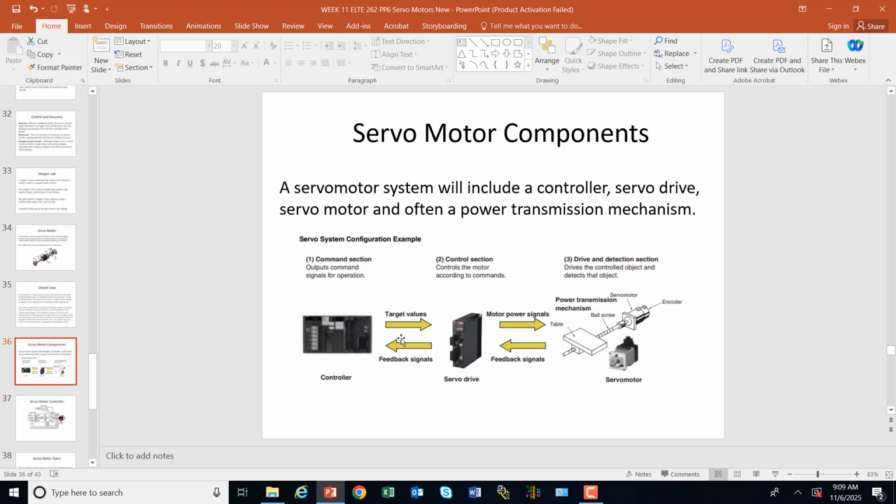And now the beauty of this is there's feedback all the way through here. So, this servo motor is an output, but it's producing analog signals used by the servo drive that can be monitored by the PLC if you want. And if you want to do a PID or something, the PLC could then change the target value of the servo drive, which would then change the performance of the servo motor, which is then going to tell it how it's doing, and you could feed it back to the controller and modify these things.